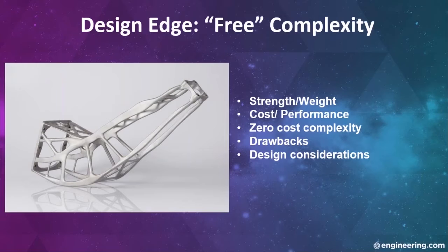Now, for a designer, it's tough to beat this from a strength-to-weight ratio perspective. And where high performance is the main criterion, well, this technology wins that cost to performance ratio contest too. And parts like this can be designed with almost unlimited complexity and internal structure with little added cost to make the part. But that complexity isn't quite free. The low-cost way to generate these optimized shapes is through generative design software. And for critical applications, performance simulation and simulation of the build are important too.